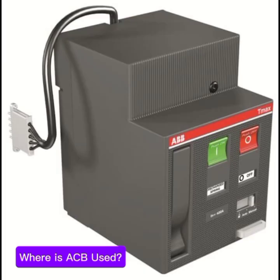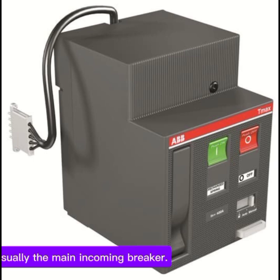Where is ACB used? ACB is mostly installed in main LT panel, power distribution boards, generator output panel, transformer LT side, bus coupler panel, industrial MCC panels. It is usually the main incoming breaker.